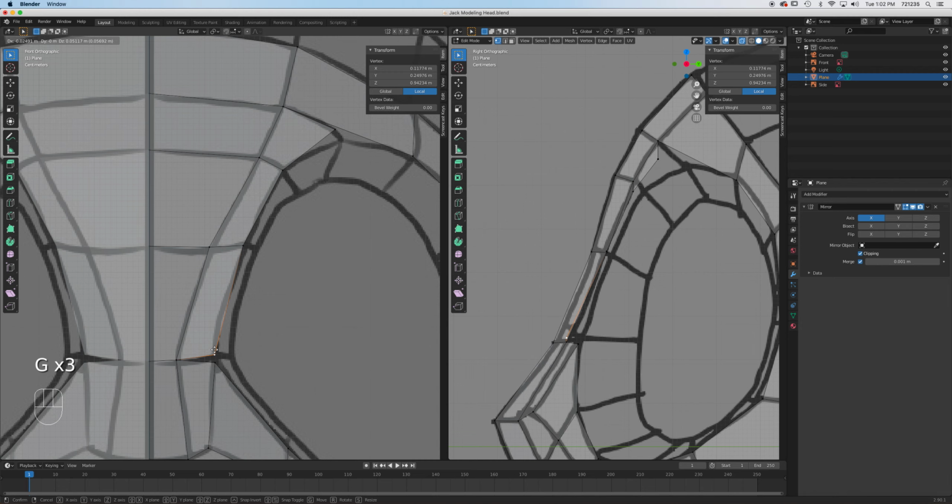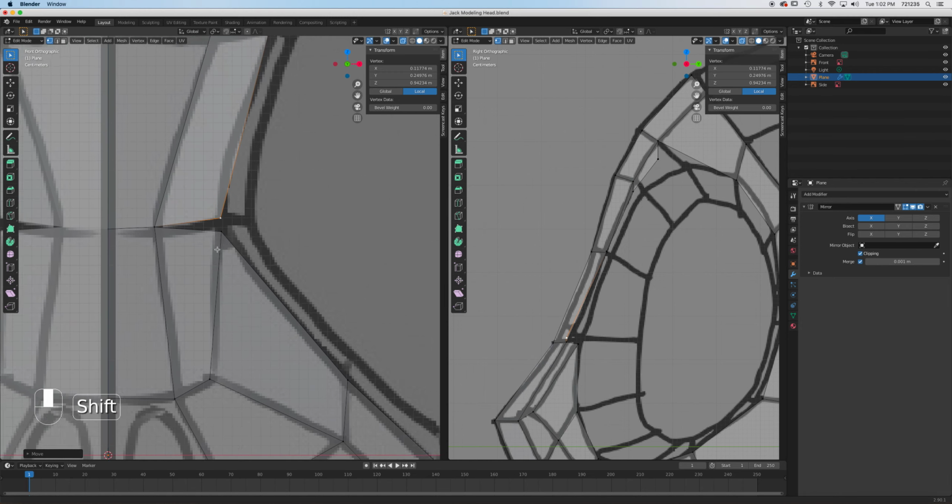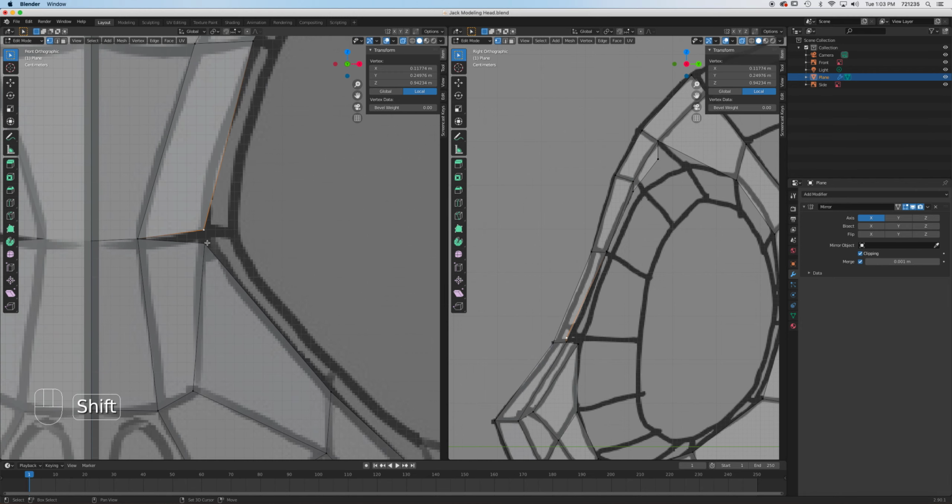All right, so now we're having issues here with that point not connected because we just grabbed it and extruded. So this is how you merge points. Select that point and then that point right there. Since you selected this first, you want it to snap to that, your last selection. If you do it the other way around, if I select this first and that one, then you want it to snap to the first. If you select them both, doesn't matter which one you selected first, you can meet them in the middle, okay? So I'm just going to do first and then last, okay?